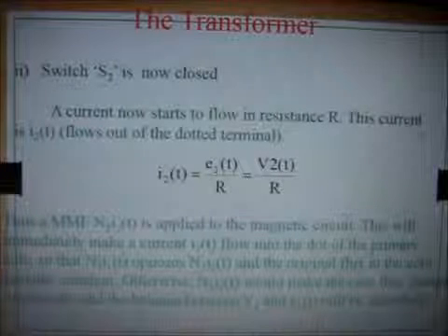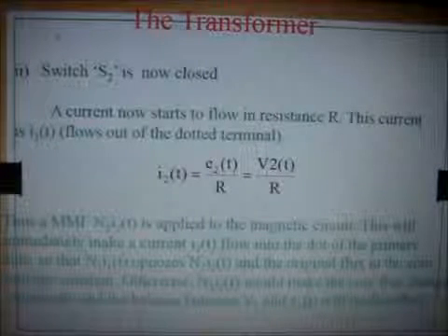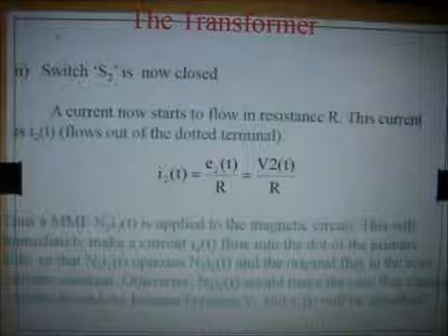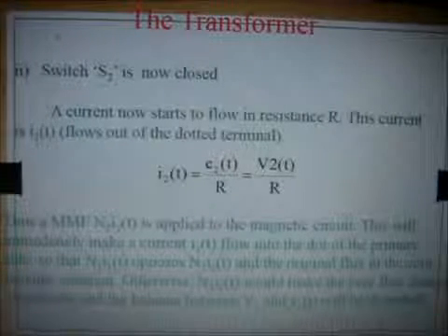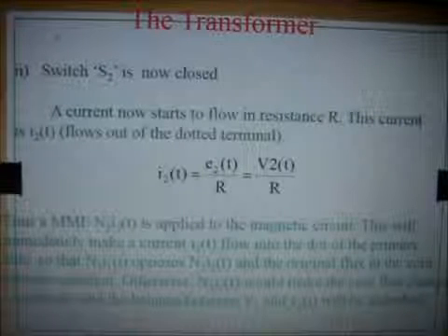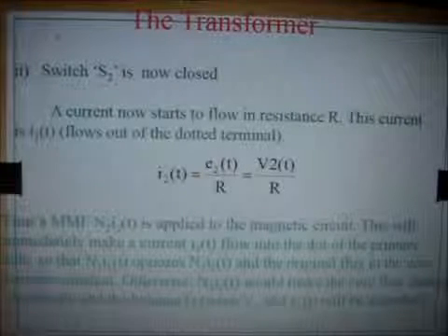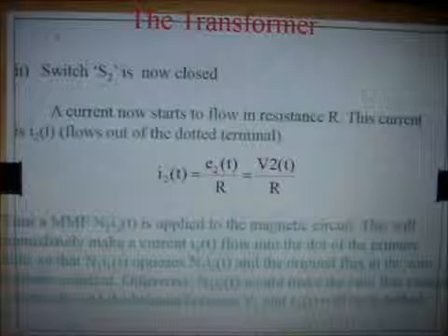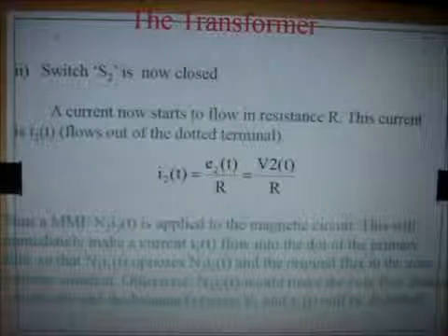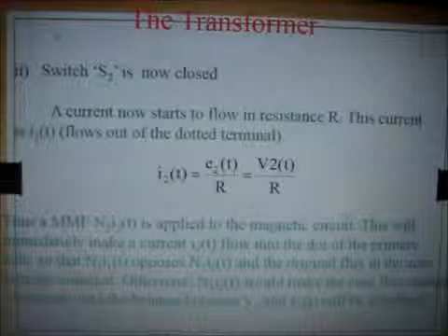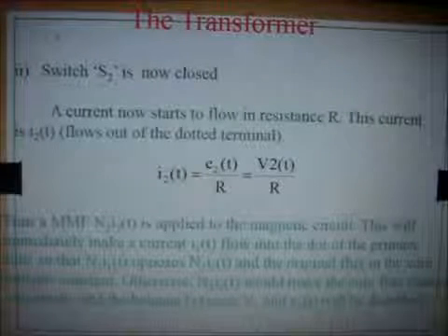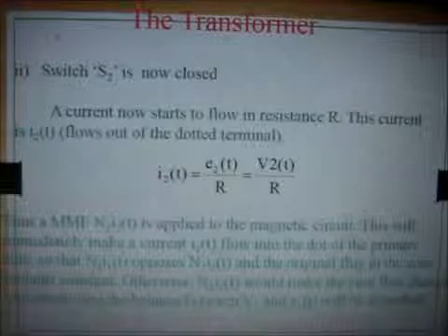If this doesn't happen, then there will be a disturbance in the core flux, and there will not be any balance between V1 and E1 on the primary side. So it is very necessary. And one more important thing in a transformer is that the frequency always remains constant from the input side to the output side, may it be a step up transformer or a step down transformer.